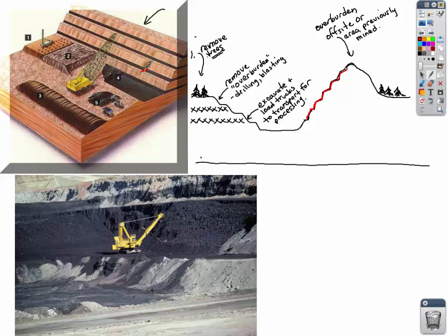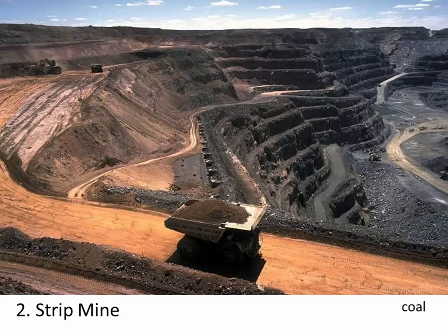The steps, the flat part, are called benches, and the angled part is called the batter. The series of them we call steps. So the benches and the batter make up the steps, and that procedure helps contain rock falls. Sometimes you need additional ground support, things like rock bolts and cable bolts. If I go back a slide here, you can see the series of steps, benches, and the batter.